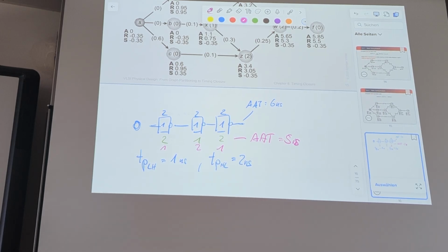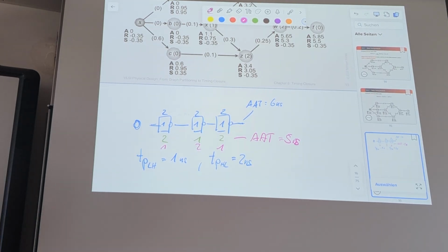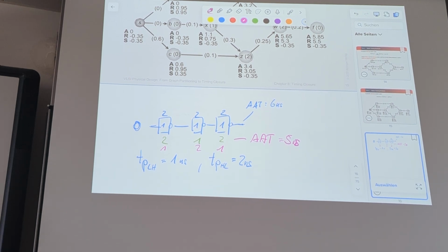Static timing analysis will be correct, but it might be too pessimistic. Maybe it works faster, but you have a guarantee when you do this STA analysis, the static timing analysis, it will run at that frequency that you have proven. Maybe faster, but in any case, it runs at that speed. And adding more smartness into the algorithm, that's what's in there today. So you add rising and falling transitions, you get better estimations of your times.